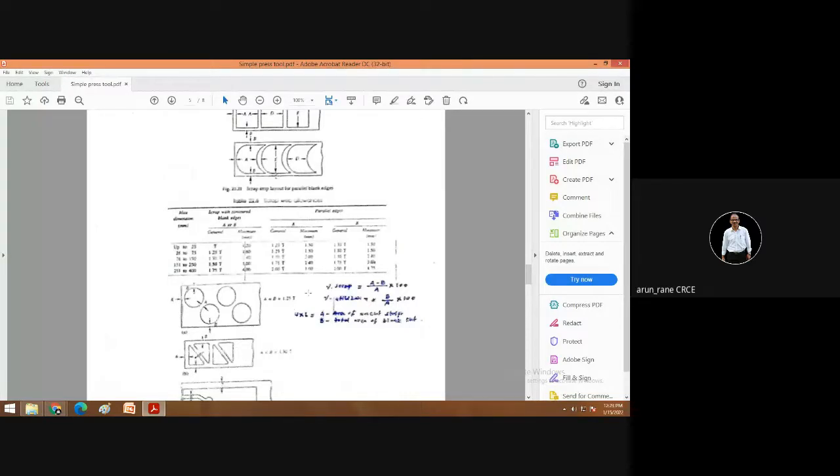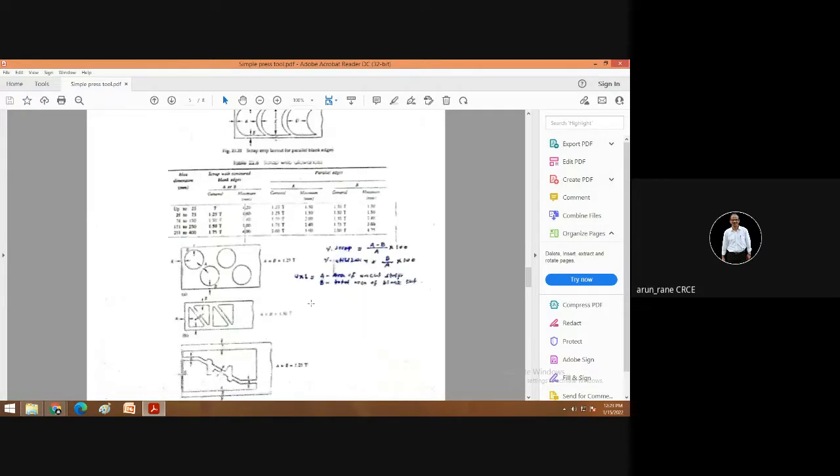So the percentage scrap will be reduced and utilization will be increased. Such a kind of design, say, a right angle triangle. If you take one after the other, then obviously it is going to cost you a lot. But if you take it like this, then your scrap will reduce and your utilization will also improve.